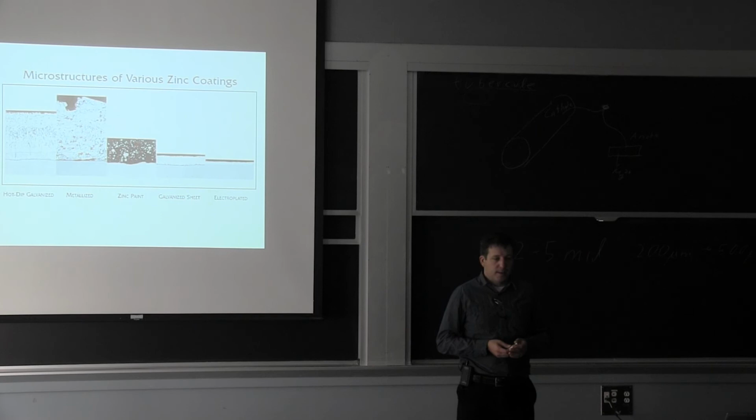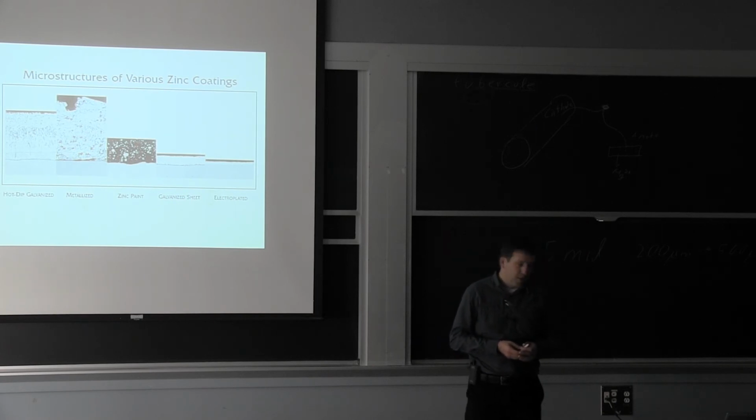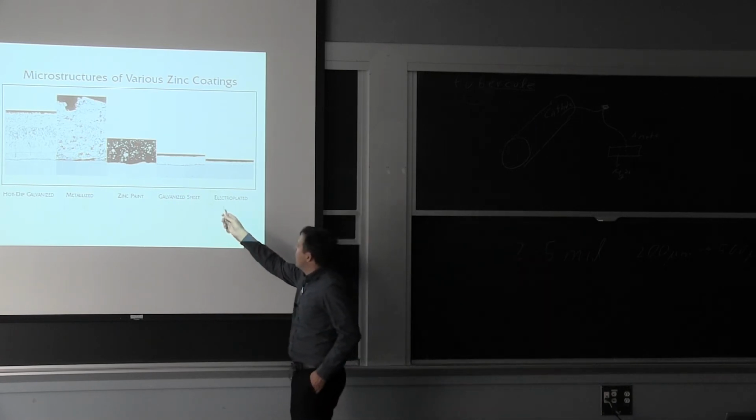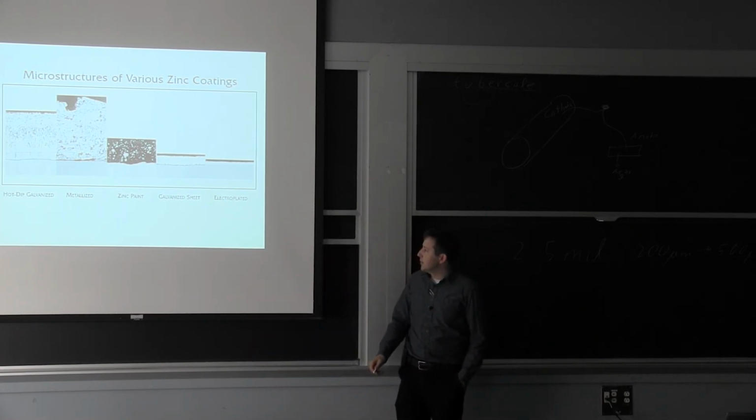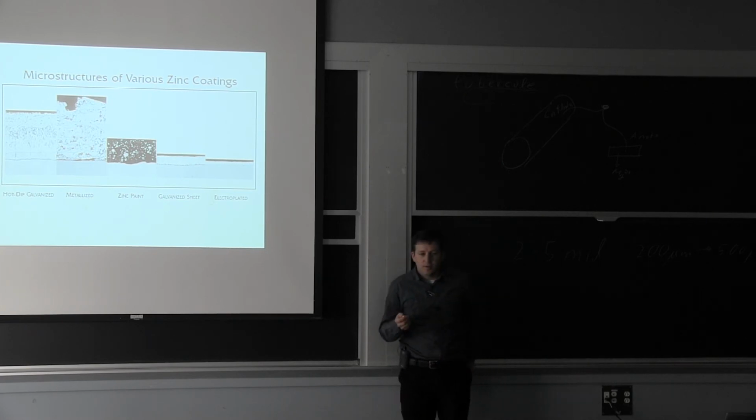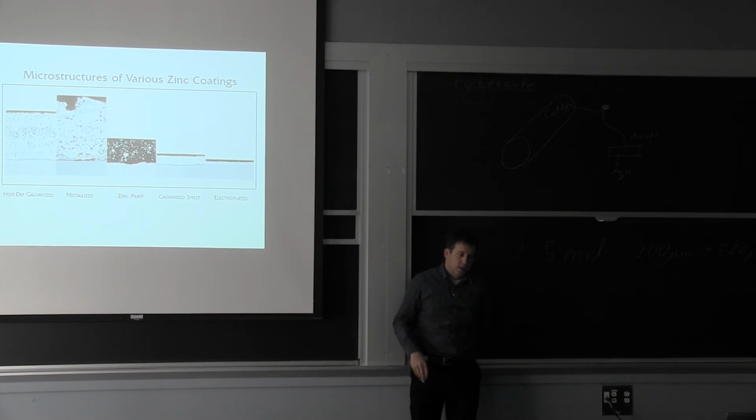And that's why a lot of times for car body panels, you're actually going to a much thinner layer that you can generate. With the car body panel, they still drop it in liquid zinc, but for a very short period of time, and then they clean it up, and they do a post treatment to create more adhesion with the surface, to roughen that surface, because one of the biggest issues of galvanizing is adhesion of coating.